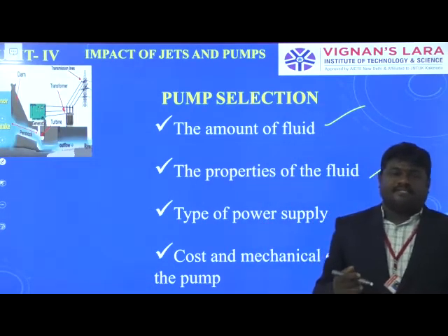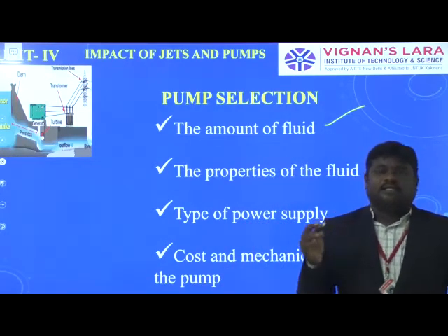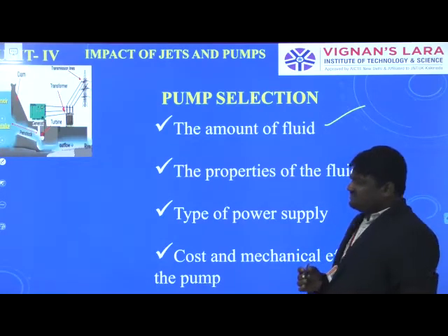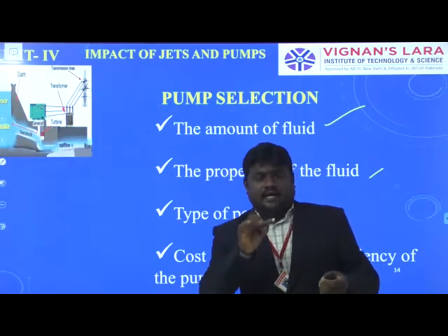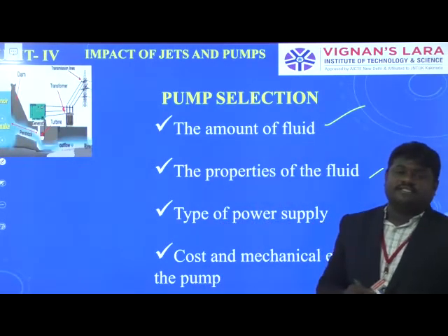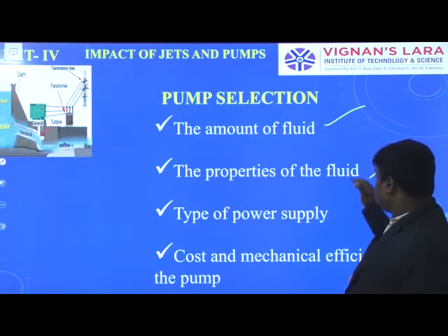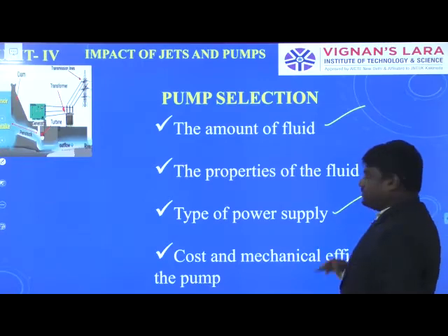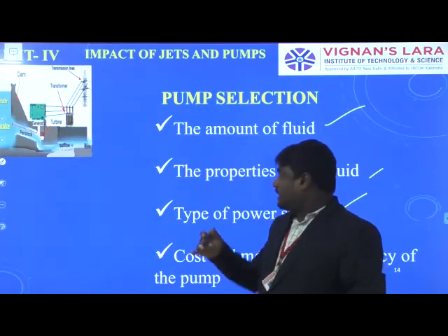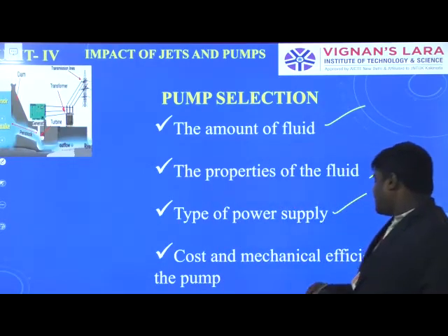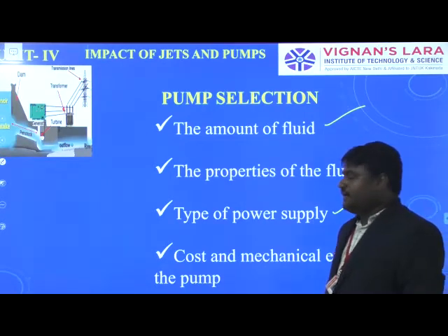So some of the properties of the fluid, if you take water, the density value we know is 1000, and the viscous force, the calorific values and the thermal conductivity. Some of the standard fluids are there, and we have to remember those values. The properties of the fluid and type of power supply: which type of power supply we are using, we have to select. Then cost and mechanical efficiency of the pump.